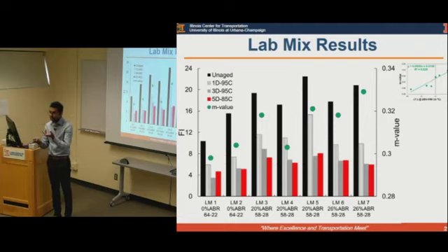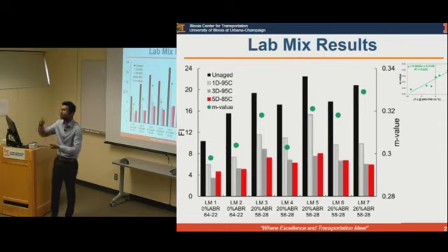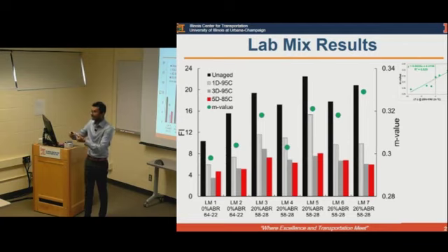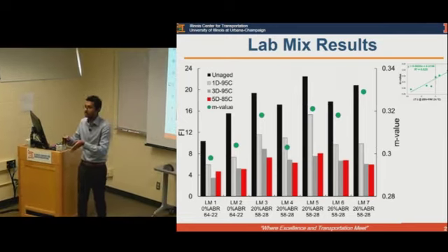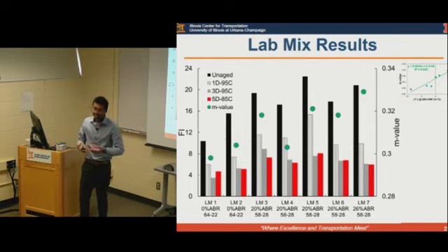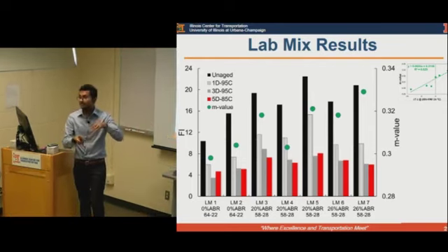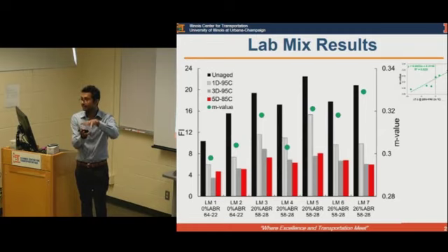I would use the analogy of how you take an X-ray image: you bombard the material with an X-ray beam, which has a specific energy, and that removes electrons from the material, and somehow that makes the image. Similarly here, UV is an energy source. It has a wavelength from 300 to 400 nanometers. Now that energy hits the asphalt binder material, and it causes that oxidation reaction to happen.